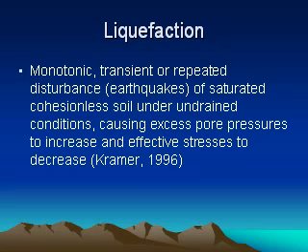In order to talk about lateral spreading, we first must define liquefaction. Liquefaction is a monotonic, transient, or repeated disturbance of saturated cohesionless soil under undrained conditions, causing excess pore pressures to increase and effective stresses to decrease. These movements are typically caused by earthquakes.